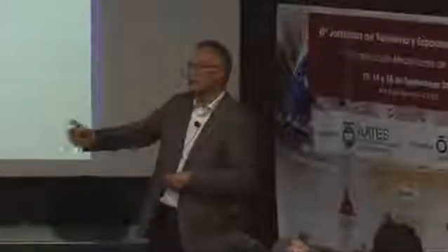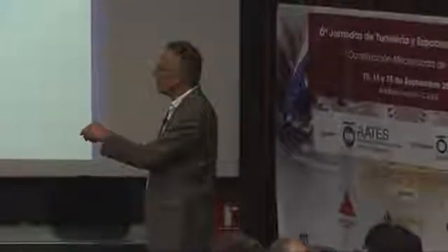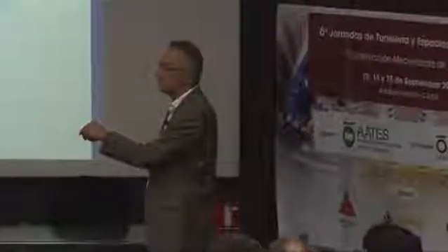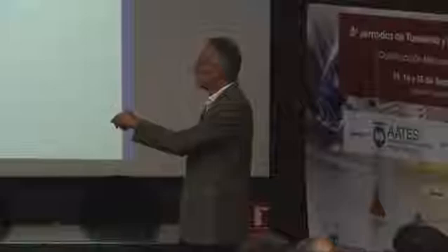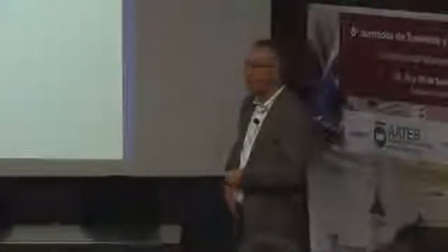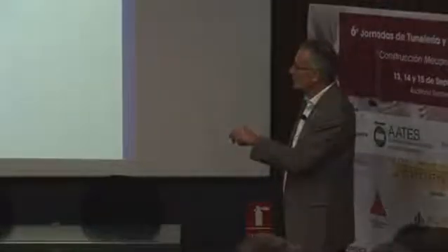As it penetrates now into it, slowly, it has more time to penetrate, you see that the pressure gradient is moving as well. So your front line is now here, it's not there anymore at the tunnel face, it's now a little bit deeper in. So your acting pressure difference is decreasing, it's getting smaller. That was over a night, but on Friday night you go for the weekend, it has even more time to penetrate. And so it grows further, and with the growing, you see here that your pressure difference gets smaller and smaller.